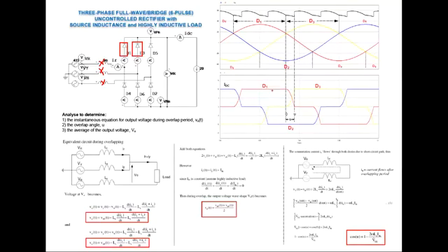The D1 current will jump from IDC, which is the current at the output, to 0 instantaneously with a sharp change. And the yellow phase current will also jump from 0 to IDC instantaneously without the source inductance.